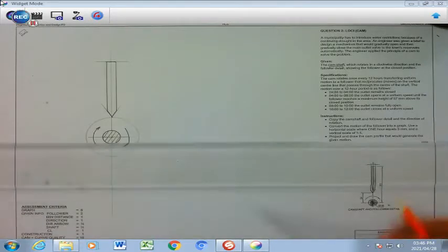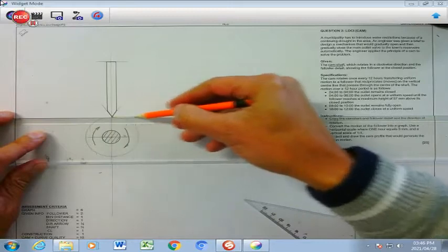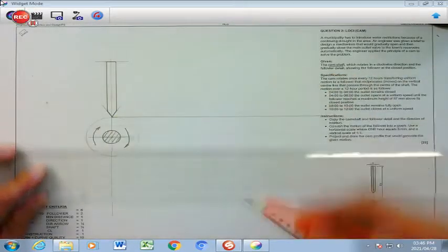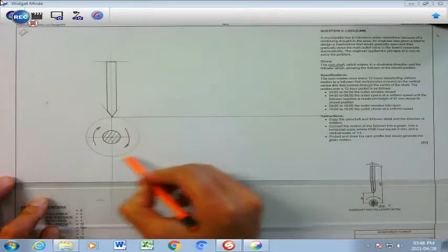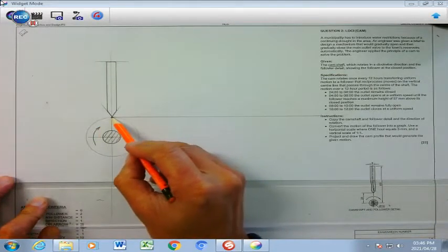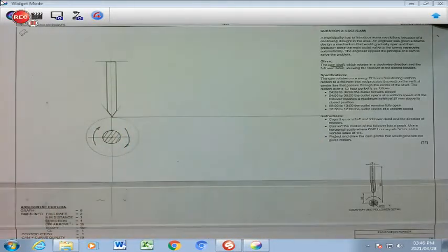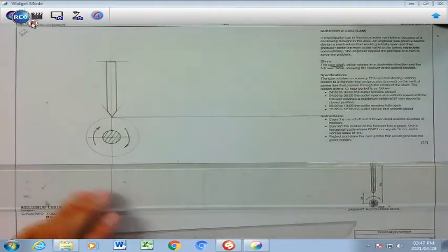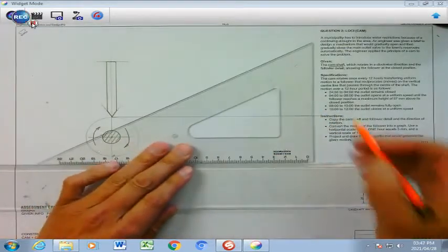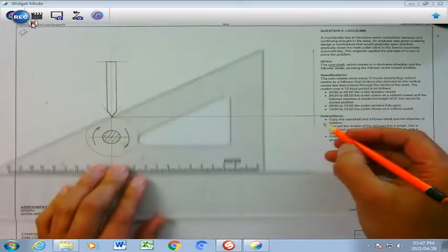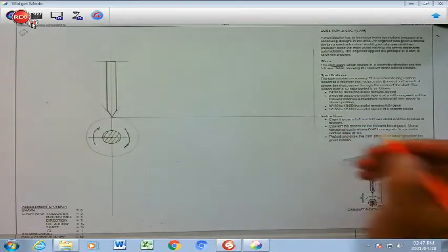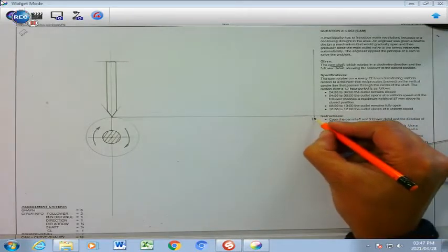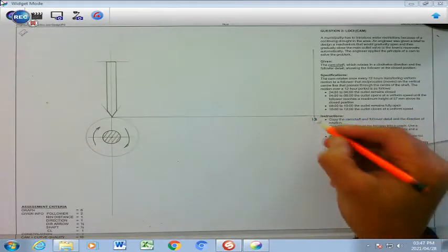And then of course the tip always forms my base of my cam displacement diagram, or the circle which I have there, which is in the same line, forms the base of my cam displacement diagram. Now I'm going to draw a starting line or a finishing line at the back there, and because we are busy with hours, I'm going to make that 12 hours. If it was degrees, it would have been 360.